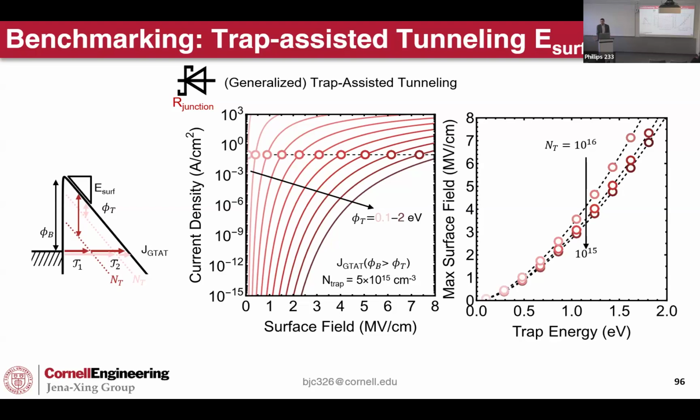There was a recent paper where they actually looked at electromigration of nickel. At these high fields, you do see defect generation natively, just because of such high fields moving impurities. In that paper it was nickel throughout the lattice, seeding gamma gallium oxide, which then leads to failure. So even in a perfect material, you get this defect generation, which then lowers the Emax you can actually reach. The refractory layer in between.